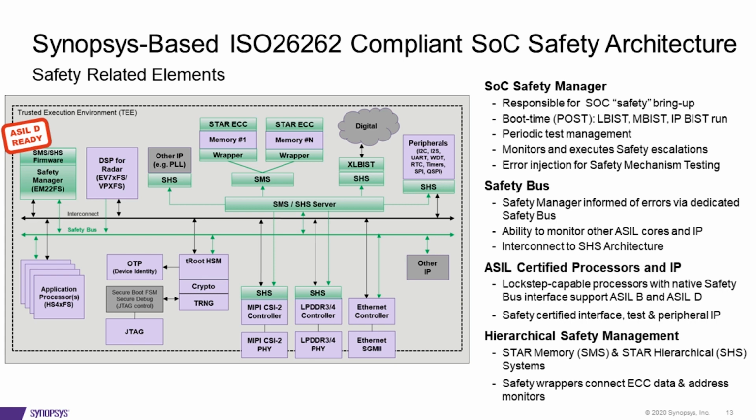That safety manager itself is responsible for the overall safety bring-up of the device. It's basically responsible for running logic BIST and memory BIST at boot time. So as the product boots up, it needs to run those algorithms. And then, as required for making sure that you have periodic tests, you will have windows where you will run all of those algorithms and run periodic tests, and that is all managed as well by the top-level safety manager.